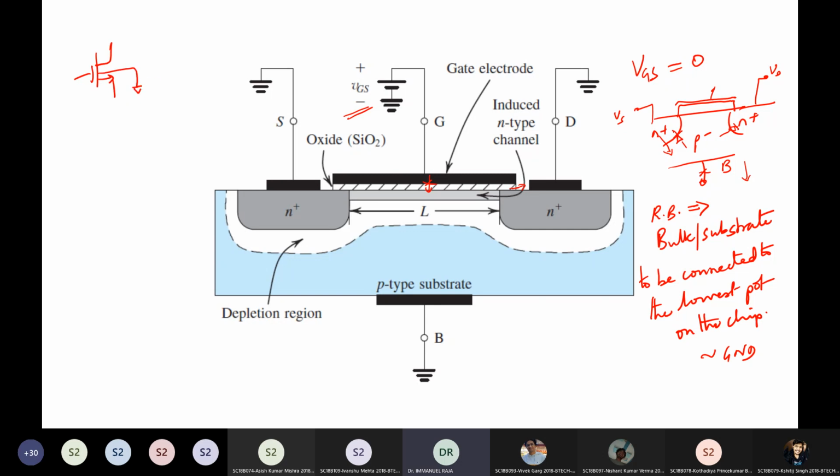All right. Okay. Now we will also see what happens. Now when your gate voltage is at 0, there is absolutely nothing there. So the current ID is basically 0. All right. Now, as you increase VGS, what happens? Now, there is a positive potential on the gate, right? Now, because of the positive potential and the bulk being grounded, now what will happen? There is no current flow here, and therefore, this particular region immediately under the oxide is going to attract all the electrons.